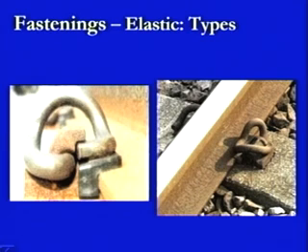This pressure has to be created while fixing these Pandrol clips, and the clip at this location goes inside this section in this way. If you can take out this one, then everything is out. Therefore, that is why Pandrol clips are in a theft prone condition.